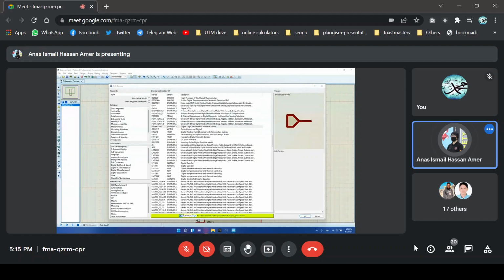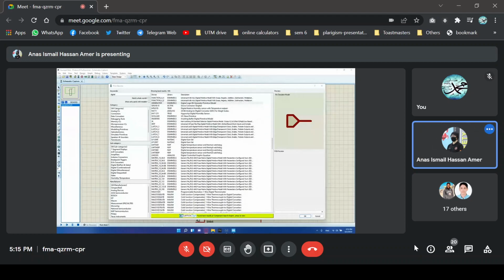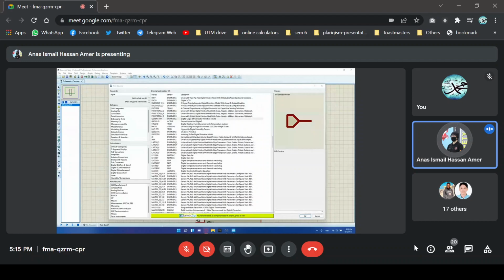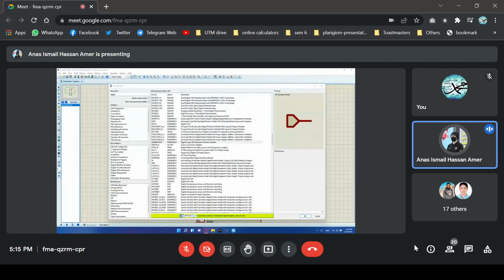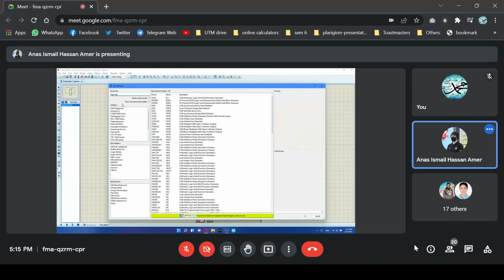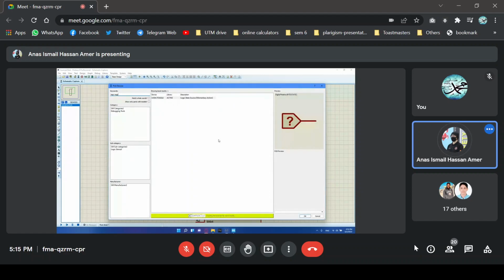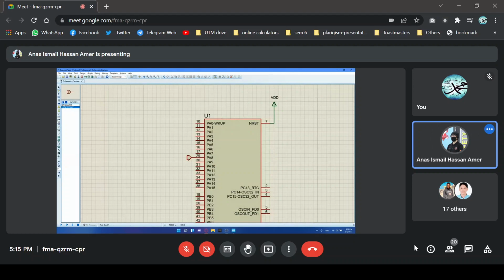So we're going to use something to relay either 1 or 0 to the microcontroller. That way we can simulate the switch or the sensor when the runner passes. So you can select the logic toggle. This one. Same, but just has some animations to help us visualize. We'll attach two, let's say A7 and A9.